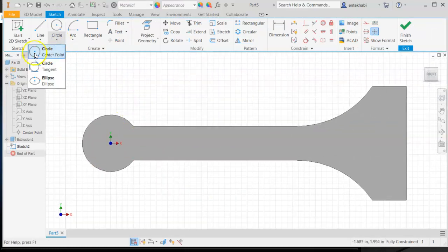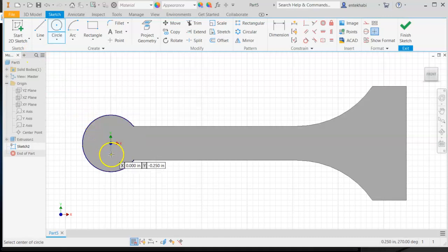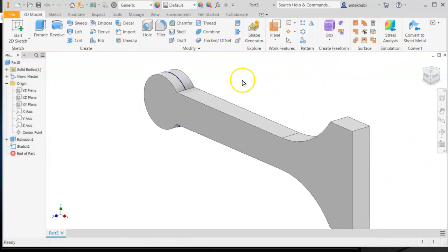Draw a same size circle in the same location, connecting to the origin, and snap into this corner to make it exactly the same size. Try not to add any dimension and constrain it without any dimension. This way, the design intent is that future changes will update automatically.